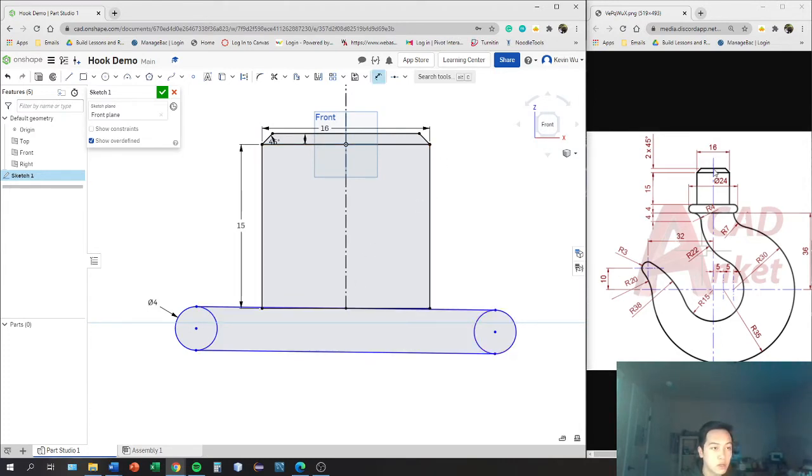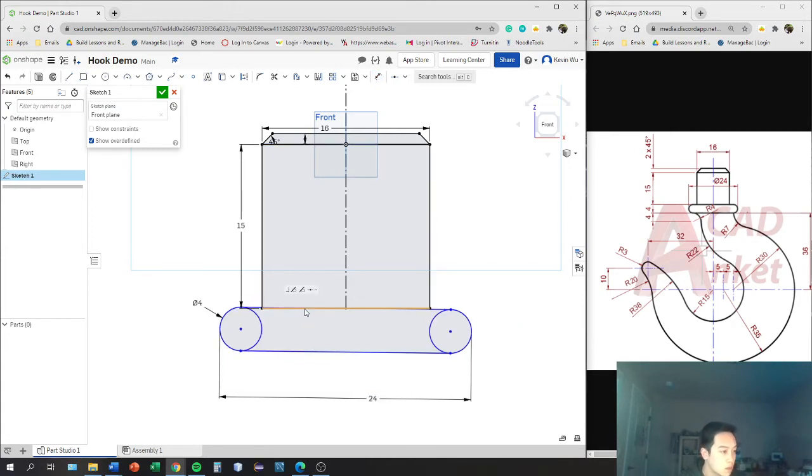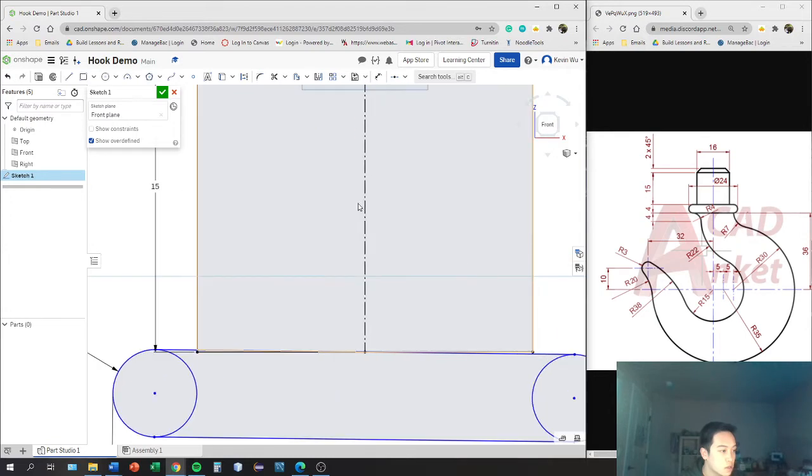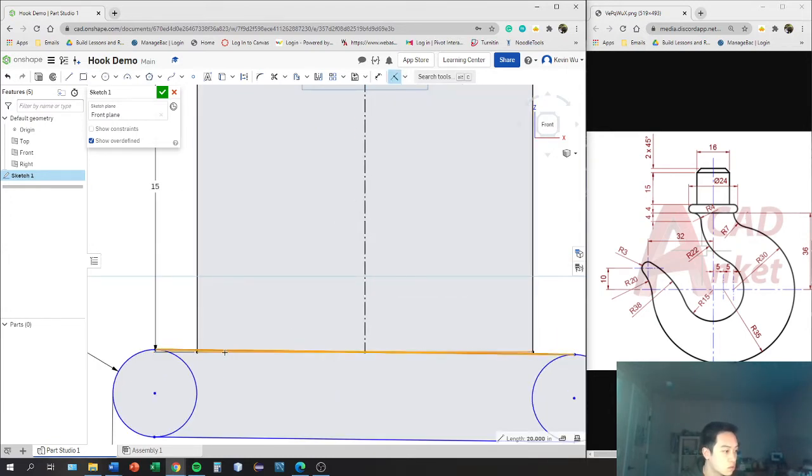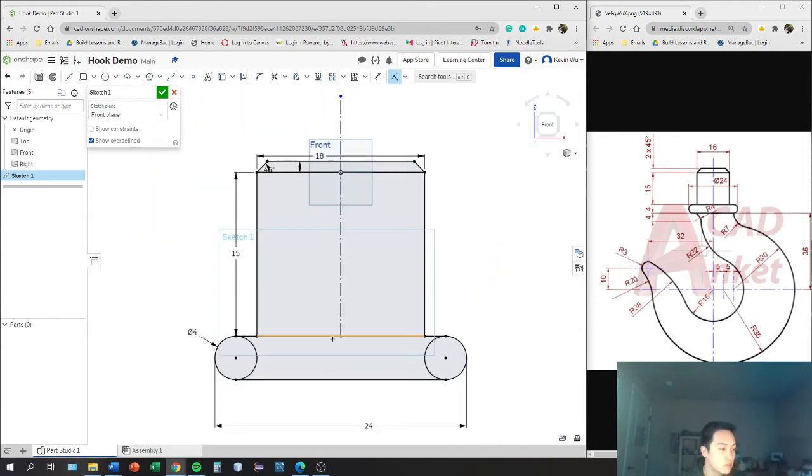Also to note that this is 24 inches in diameter, because technically this is actually a circle. This is why the symbol is a 0 with a slash in it. So 24, and I think mine is a little off, so I'm getting coincident. If that happens, all you have to do is make the two lines coincident together, and that should work.